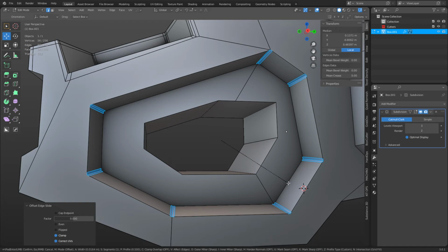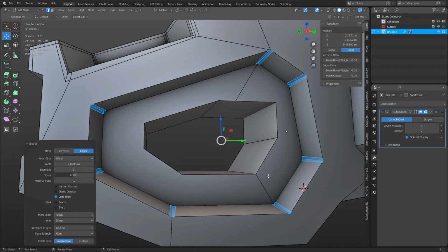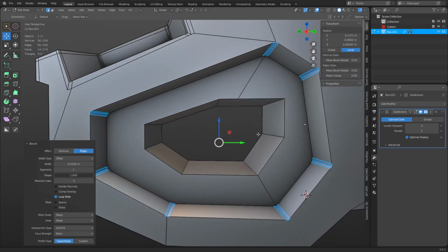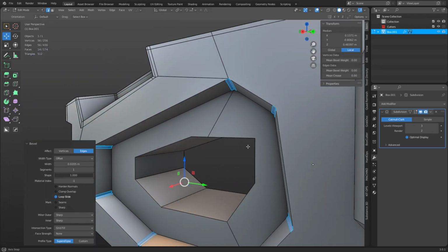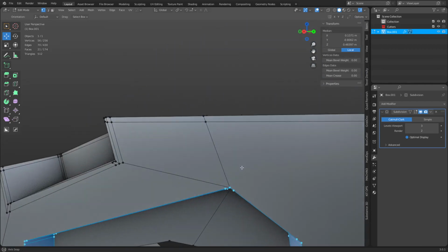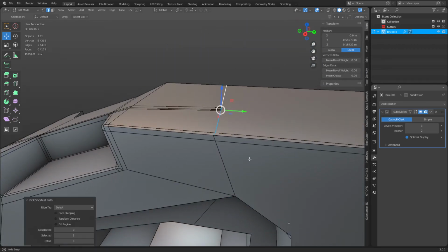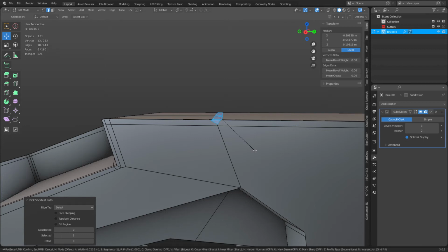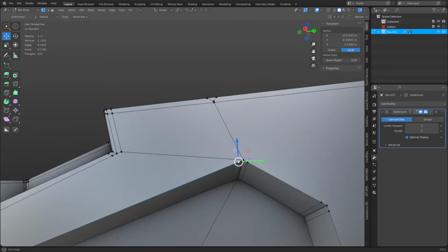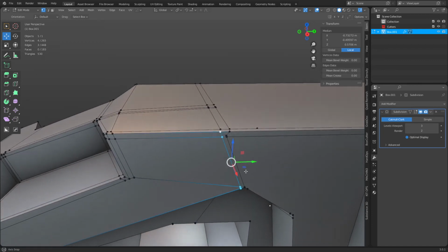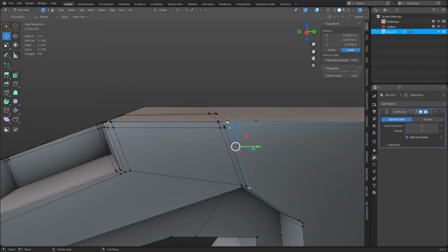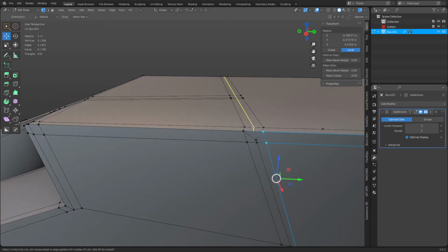And let's do a bevel. Keeps doing that. When you do the bevel, you could change the shape to 1. All right. Just a heads up, I've run into a bug with that as of late, where if I change it back to 0.5, Blender will actually crash on me for some reason. So it's kind of a weird situation, I guess, but just want to point it out in case you run across that. So save your work, definitely.